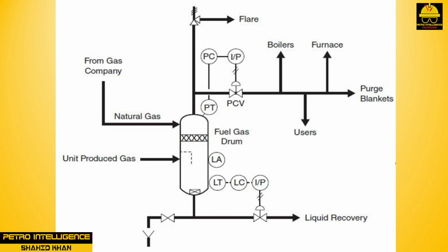Fuel gas generally consists of plant-produced process gas that is augmented with purchased natural gas to satisfy the unit's energy demand. Fuel gas required is typically produced internally during normal unit operations. During a startup mode or emergency mode, where no internal fuel gas is available, gas is imported. The imported gas is measured in a meter station before entering the unit. During normal operation, any excess fuel gas produced is exported by a compressor system.